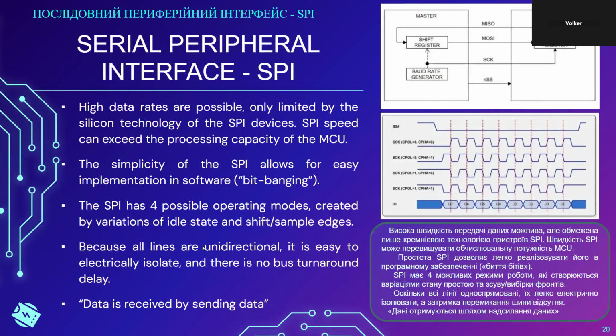You can basically just say GPIO pin up, GPIO pin to 0, and then set the clock lines. There are no wait states. It can all be done without any waits. So there is not much time that is being lost. There is not much processing power that's being lost if you implement it.